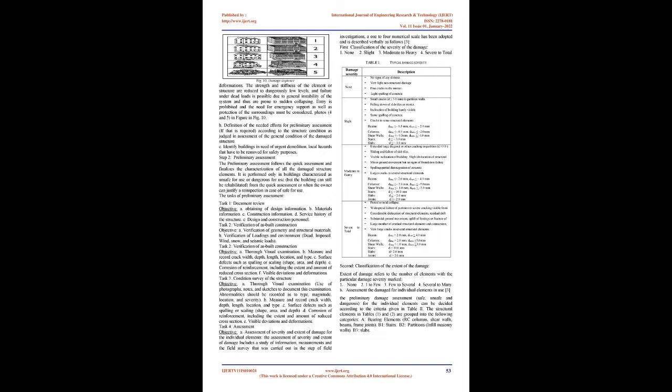Task 3, Initial Visual Examination. Objective: A. Determine the general case and take an initial impression regarding the condition of the damaged structure. B. Visual inspection of the damaged structure, the building from the outside. C. Searching for damage to all visible structural elements, especially columns, shear walls, core elements, beams, and stairways. Take photos documenting the damages.